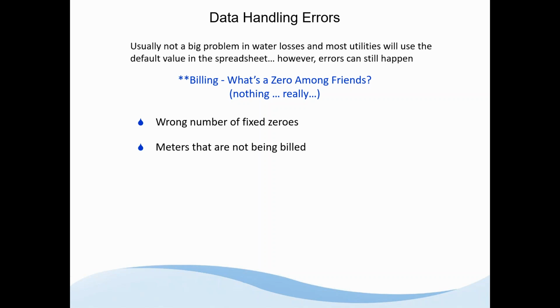We also have the issue of meters not being billed. Did something not get recorded? Register heads not being properly programmed. In this day and age of technology, that's a big deal, and that can happen, and that can mess up the information you're getting from that water meter.